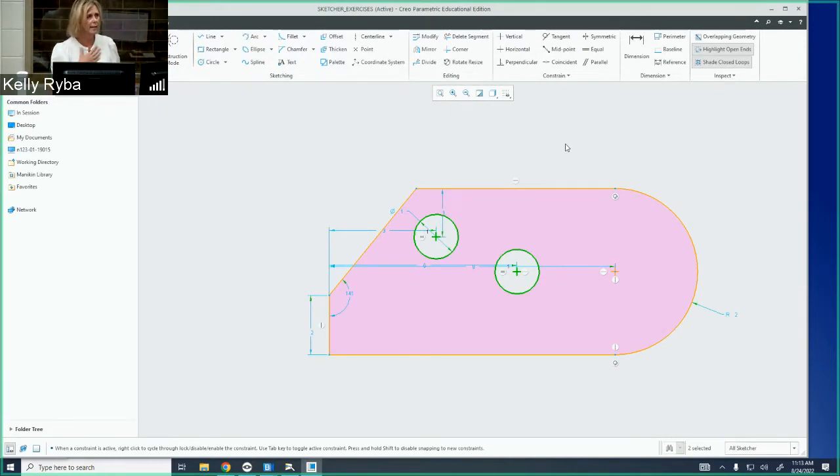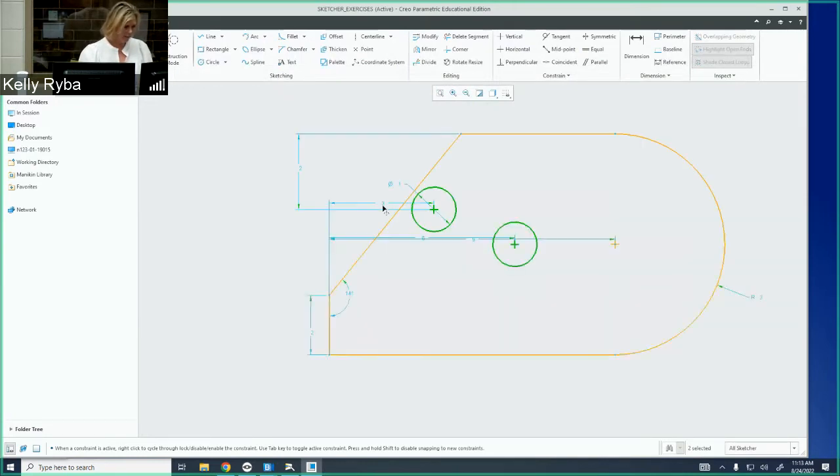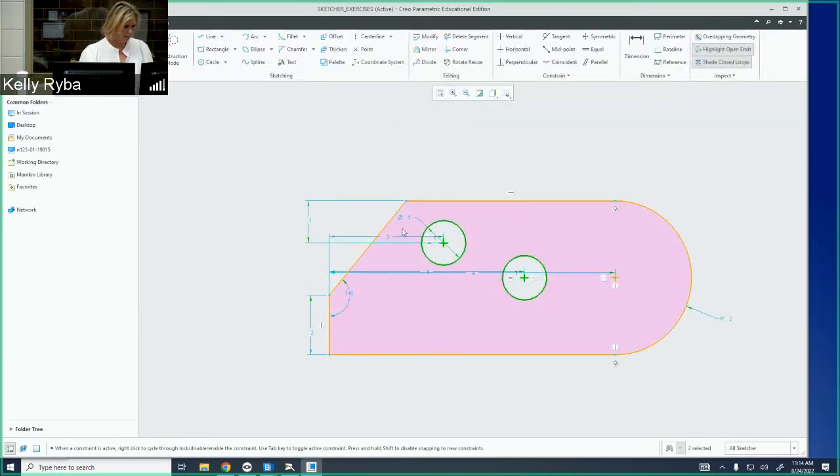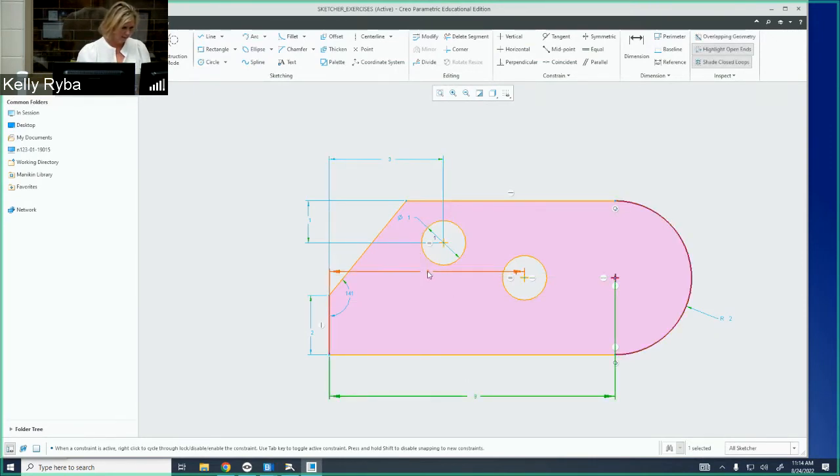Okay. Now the next thing that I like to do is I like to just kind of move these things so that I can actually make sense of them. I got to select this one, the actual, you kind of see what I did there. The dimension was close to the edge here. So when I selected the dimension, what I thought was, it actually selected the feature and it was moving it while I was pushing my cursor. I had to just hit escape to stop that. And then I went back and I selected the dimension itself. So same thing here, make sure that dimension is selected.